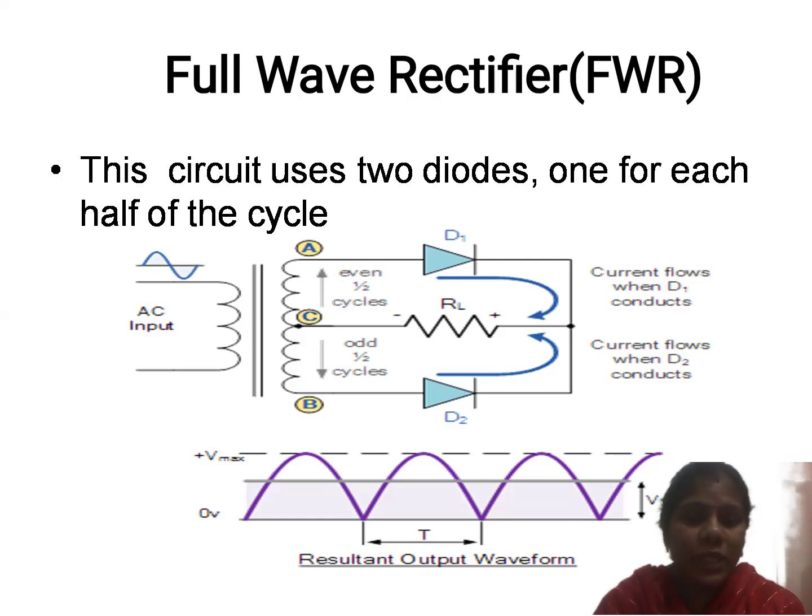This is possible by using the principle of diode operation. A diode is an electronic device which allows the flow of current in only one direction. The output is taken only from plus to minus polarities of RL, so it uses only one direction. During the positive cycle D1 conducts and D2 does not, so the output flows from plus to minus in the single direction only.